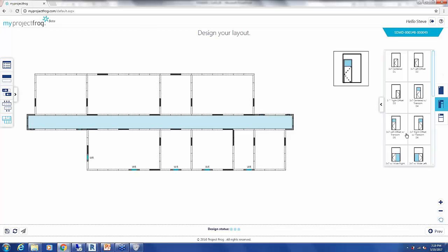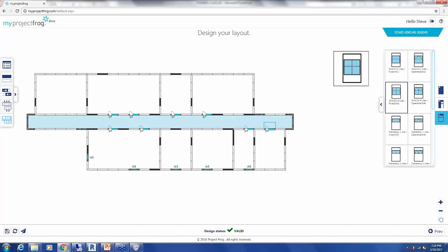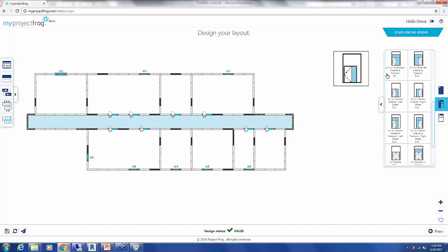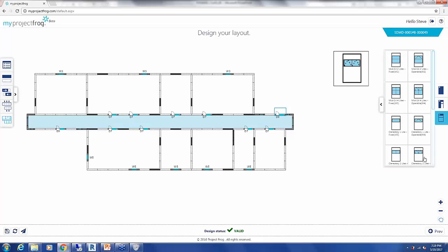So while this is thinking, I'll just drop in a few skews so you can see. I'll configure this building here in a second. We'll run it all through Dynamo, and the output is going to be a model that drives all that previous information that I told you about. So let me add in the door just to make it look like it's actually a building. Certain skews are not allowed to go in certain locations. So you'll get little red boxes, or a little Ghostbusters sign, for skews that can't go in certain areas.